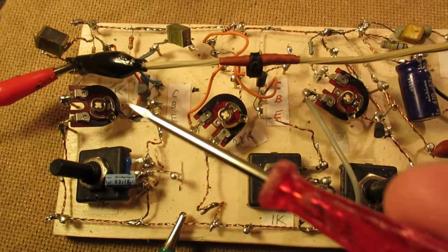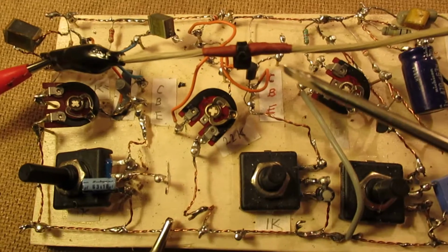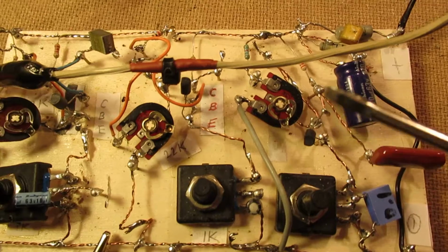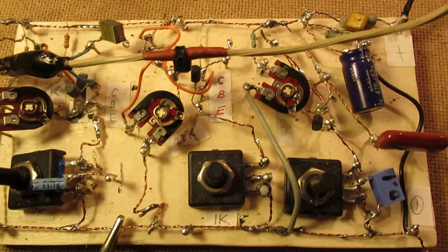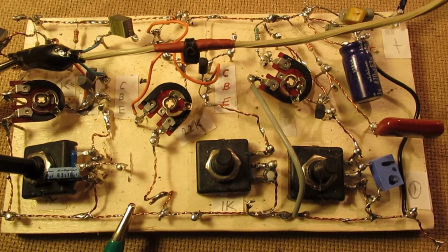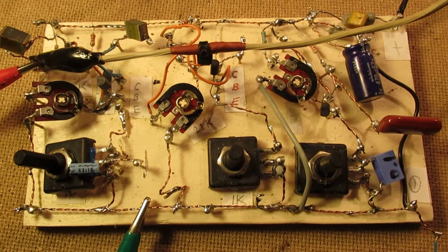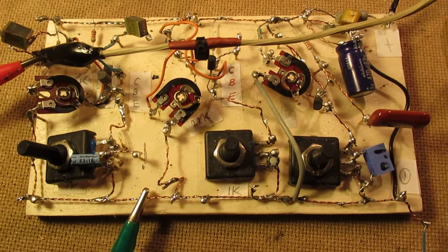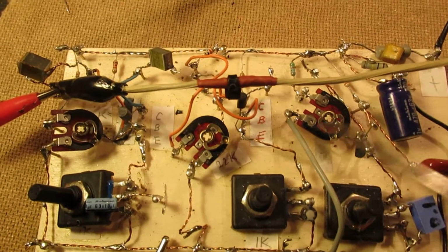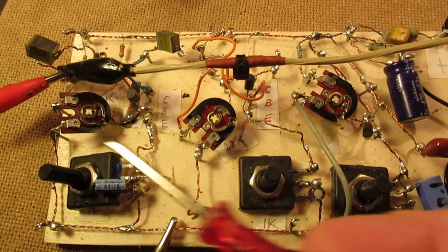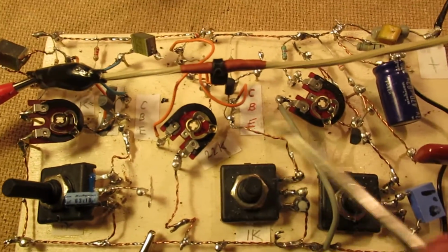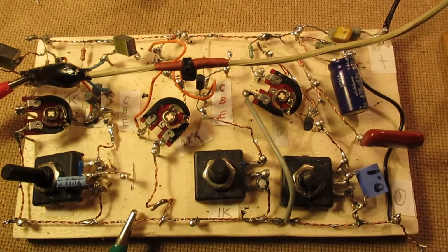Because the first transistor amplifies, the second transistor needs another bias, and the third transistor also needs another bias. And that's a flaw that you often see on many electronic websites: the same voltage divider, the same biasing, is used for all 3 stages. But to get it pure, every transistor needs its individual bias.